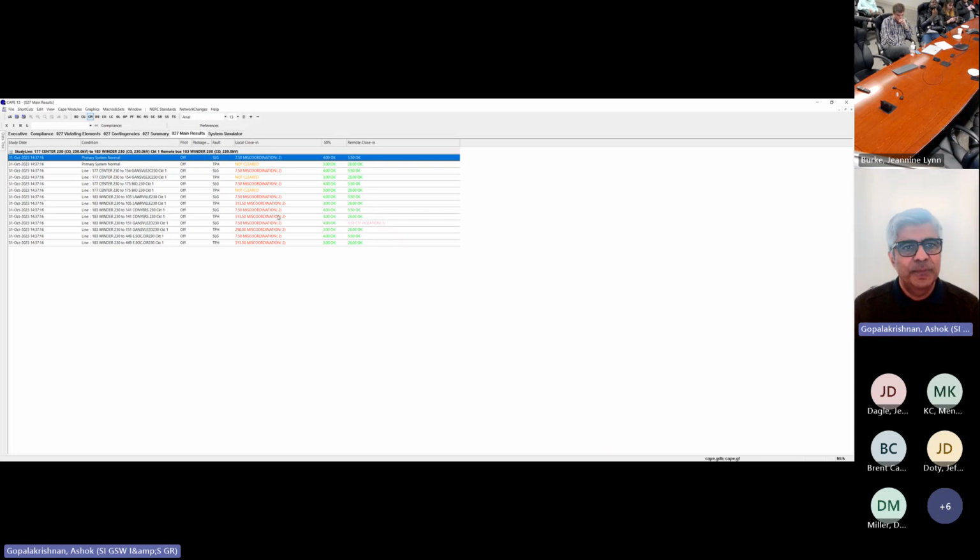So I think we should, at least for the transmission system, probably stop here, but you can extend this to multiple different lines. You don't have to stop at this one single line that I studied. You can automate this whole process so that it goes through your entire system and runs these studies and captures all the protection problems. To visualize this better, we have some tools to export the results to a spreadsheet, or